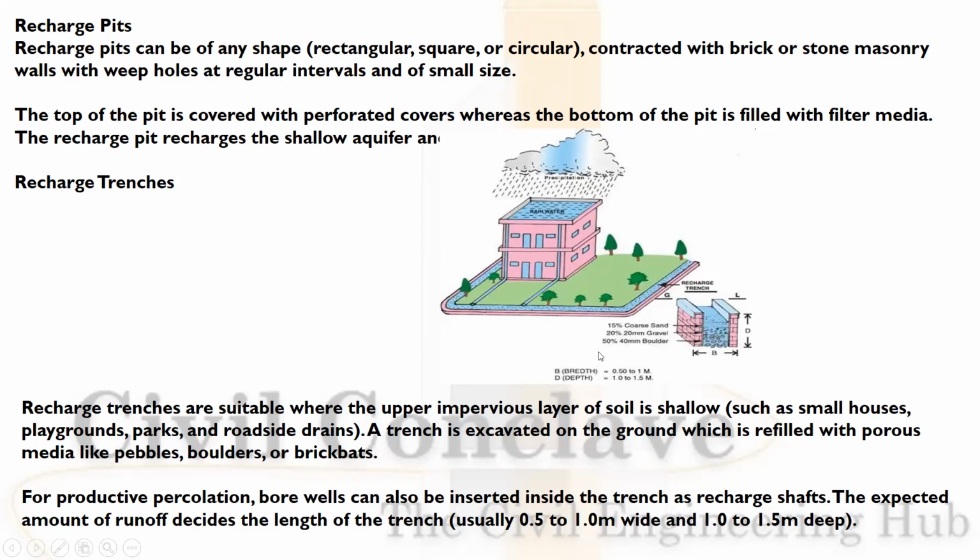Recharge trenches are suitable where the upper impervious layer of the soil is shallow. That means small houses, apartments, etc. A trench is excavated on the ground, which is refilled with porous materials like pebbles, boulders, or brick bats. For productive percolation, borewells can also be inserted inside the trench as a recharge shaft. The expected amount of runoff decides the length of the trench.